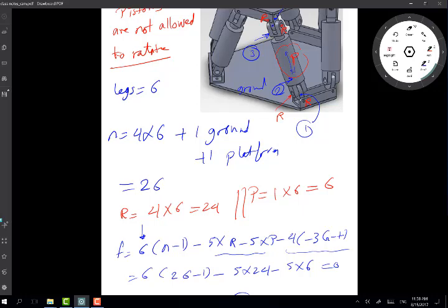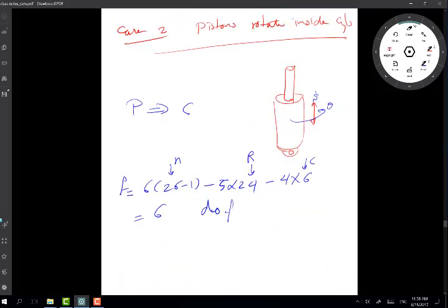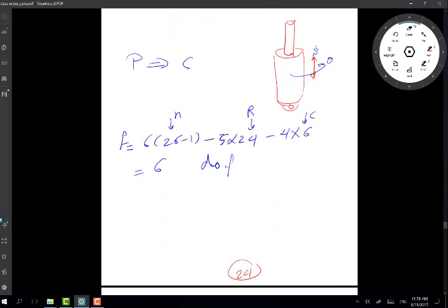In fact, if I have a design of hydraulic cylinder that doesn't allow this rotation to take place, I would have to provide this rotation myself, possibly by adding a revolute joint at the clevis end at the top here, or something like that. But if it's already provided, if the cylinder design allows this, it will just give me this extra freedom. That will be useful, right?